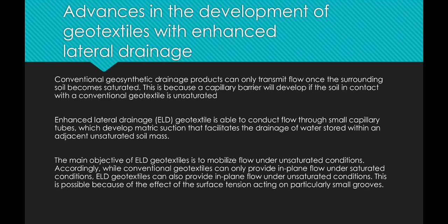Advances in the development of geotextile with adjusted lateral drainage. Conventional geosynthetic drainage products can only transfer flow once the surrounding soil becomes saturated. It's because a capillary barrier will develop if the soil in contact with a conventional geotextile is unsaturated.